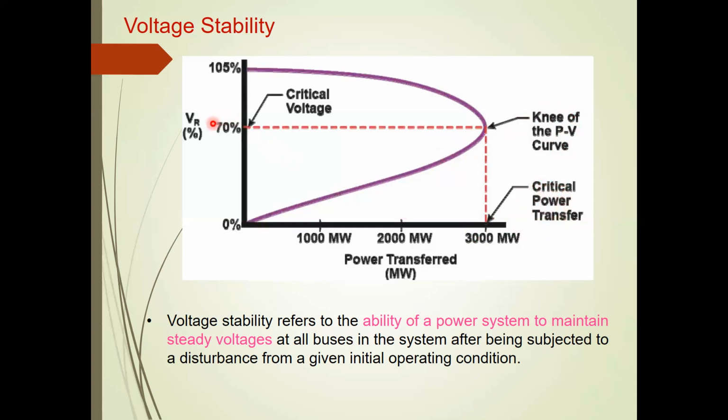Although it is set at about 70%, in some cases it can be even 80% as well. Yeah, it could be. But normally for bus network operation, at least for the transmission network, the voltage deviation of the bus should be just 5% around the nominal value, around the rated value. It should not be beyond that, right?